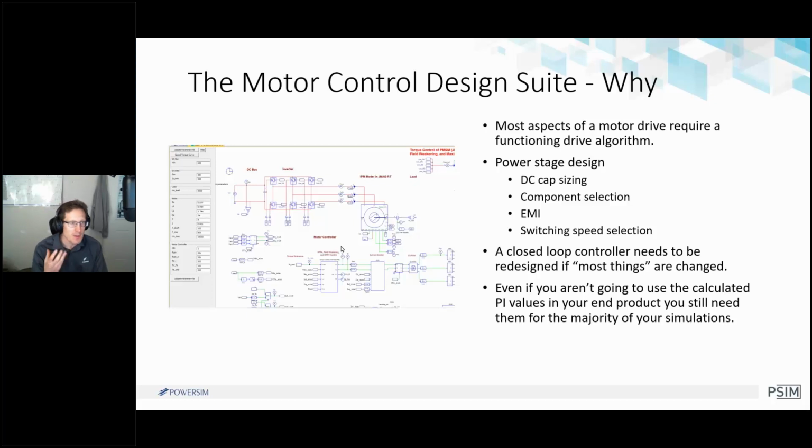You can't just slap on. It's not an induction machine. You can't do anything you like with these things. With a PM machine, you need to wrap it up properly. You need to have proper closed loop systems on it. And then if you're running advanced control algorithms like max torque per ampere control, max torque per volt control, or field weakening, these things require closed loop controllers.